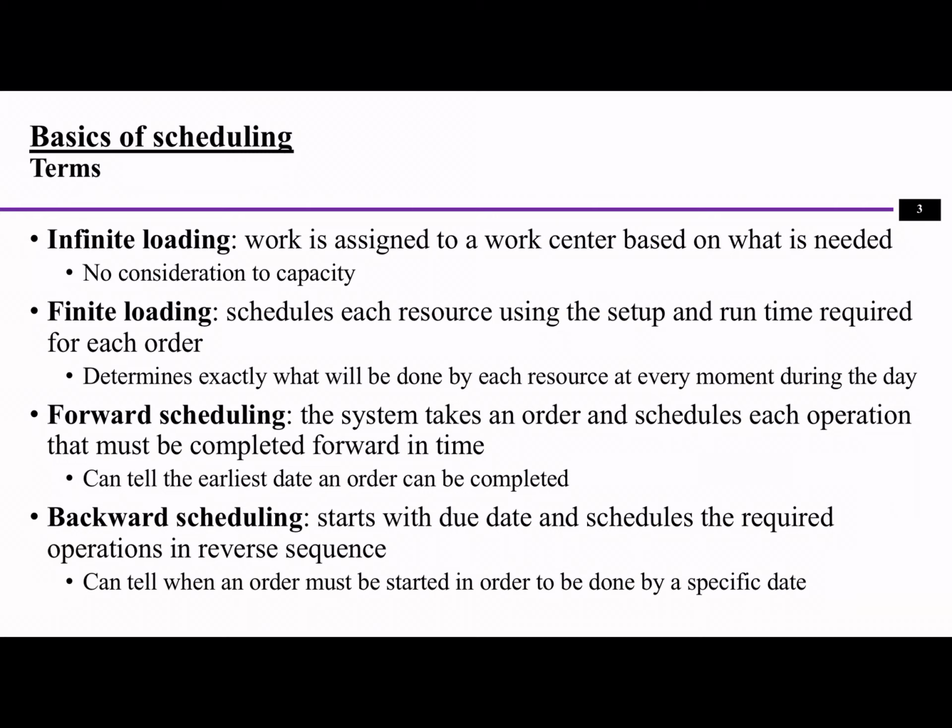Forward scheduling is compared with backward scheduling. Backward scheduling means I received the order and the order needs to be filled by the end of this week. I'll start by looking at the end of the week. That's the deadline. Then, in order to meet the deadline, I look at the due date for the second last process, and then the due date for the third last process, until I can come back to the first process and ask, what is the latest time that I need to start my order in order to finish before the deadline?